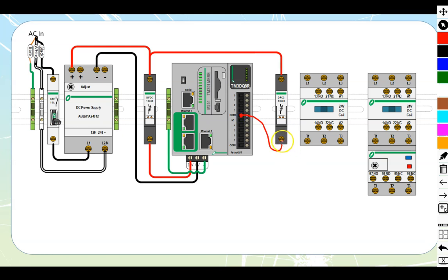We're going to bring that one into the top, and actually let's bring one into the bottom section as well, because if I wanted to wire anything out of here, I would need to run components off of that one as well. So if you're going to run through both sections, this common feeds this whole group over here. This common up top feeds that whole group over there. So we're going to bring it into both of these if we're going to run both off there.